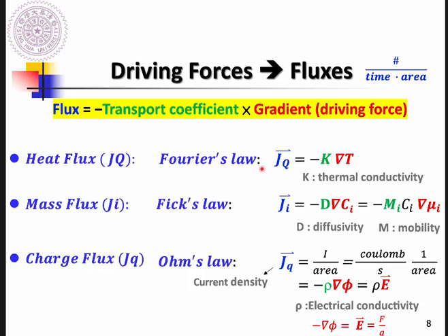So for example, the heat flux and the temperature gradient to drive it, and how to describe how fast or how slow this material transports. We use the thermal conductivity, a heat transport coefficient. And for the atomic flux, the driver is a chemical potential gradient, and the transport coefficient is the mobility or diffusivity, describing how fast or how slow the atoms move inside these solid materials.